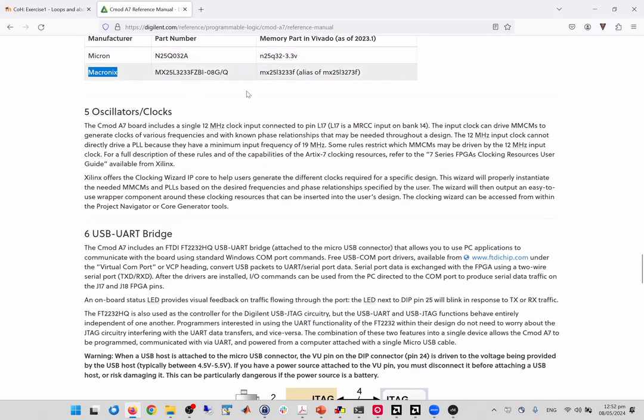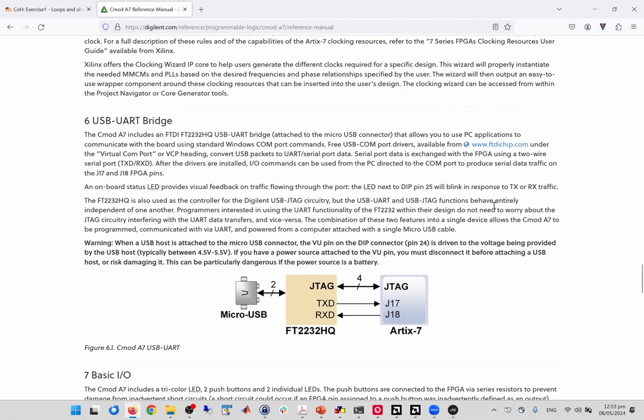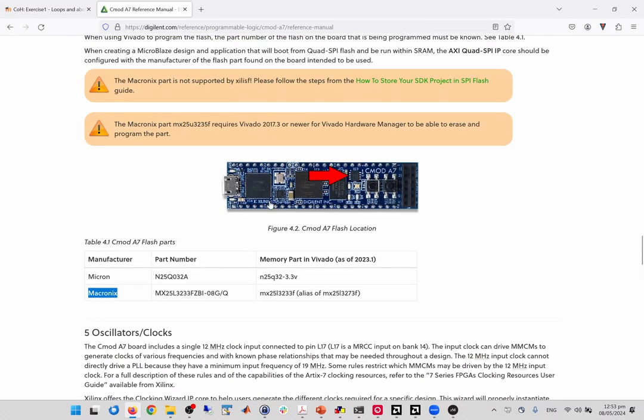And each of them should be connected to the FPGA and the PCB in a particular way. The board also has USB and USB UART bridge functionality. There is a chip on the board. If you look at the board later, the first chip connected to the USB port here is an FTDI chip. FTDI is a famous producer for converting the USB port to many other features, for example UART, COM port, or with some libraries you can communicate directly through the USB.